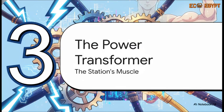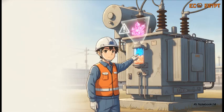Okay, Section 3, the power transformer. Now we step up the voltage. This right here is the true muscle of the station, the 9,000 kVA power transformer. It takes that 0.8 kilovolt input and steps it way up to 33 kilovolts. And the engineering here is just brilliant. It uses a Dyn11 vector group, which gives us a 30-degree phase shift and actually traps and blocks the third harmonic from ever reaching the grid.